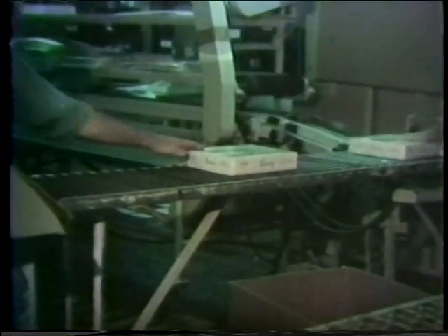The rollers are mounted so that a relatively flat surface will be presented to the material, which has to be pushed over them. By setting the rollers at an angle, the boxes can be made to go around curves. This allows us to make up systems in a number of different configurations.